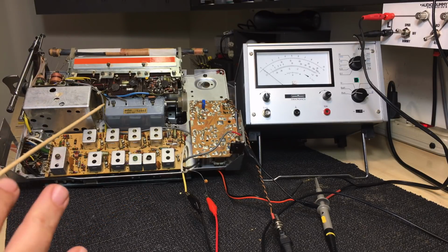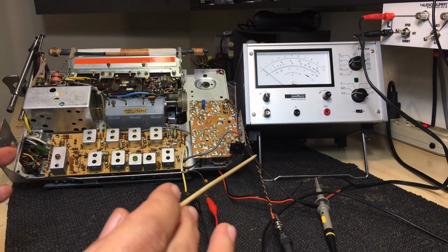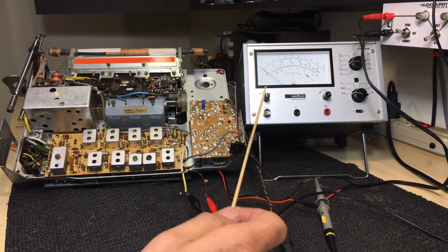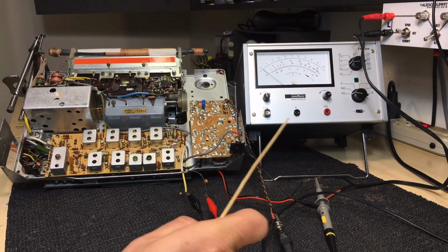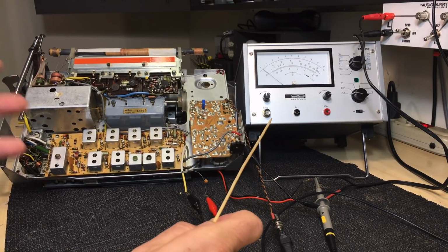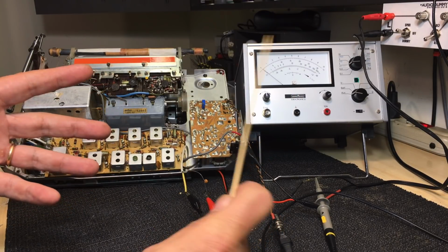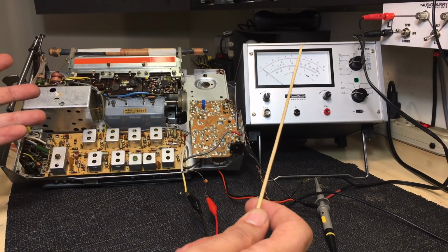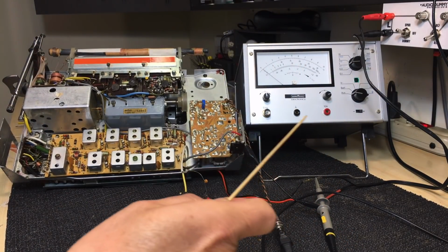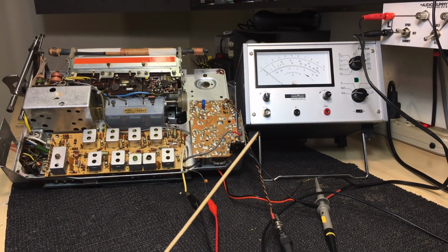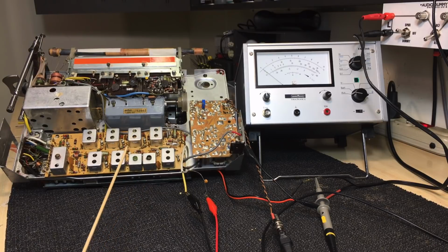And so ultimately the best way is the simplest way, which is you measure the voltage at the output, AC voltage. You've got a tone coming out, which you can hear on a speaker. If you can hear on a speaker, it's actually an alternating voltage at 600 hertz. So if you measure that in an AC millivoltmeter or voltmeter, you can see when it's at a peak. Simple, right? That's exactly what I'm doing here. I've decided to go that route because it simply makes more sense to me, and everything is set up, and we can now just go through this. I've tried the other methods and I'm not too happy with the result.